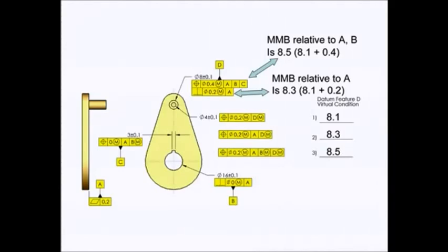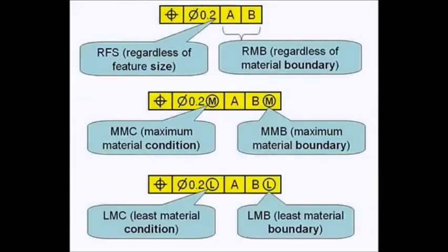Yes, and there are some new terms, and along with that we have maximum material boundary and least material boundary, so when we see the modifiers on the datum references, now they all have a common term. So there's a lot of things that have changed in the standard. We have new concepts, we have expansion of principles, we have brought it up to date with the other Y14 standards. And in about a day's time, you too can be updated to this 2009 revision of the Y14.5 standard.